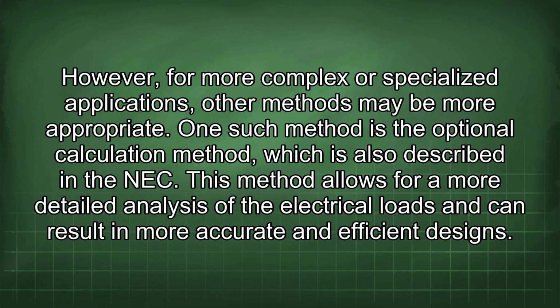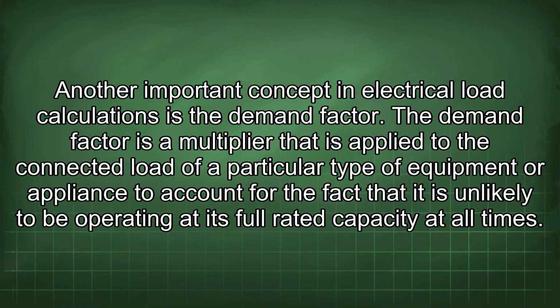One such method is the optional calculation method, which is also described in the NEC. This method allows for a more detailed analysis of the electrical loads and can result in more accurate and efficient designs. Another important concept in electrical load calculations is the demand factor.